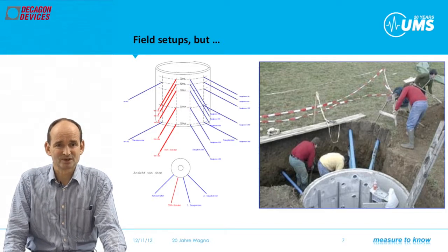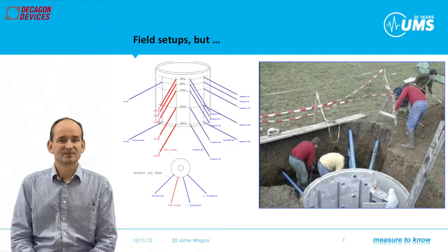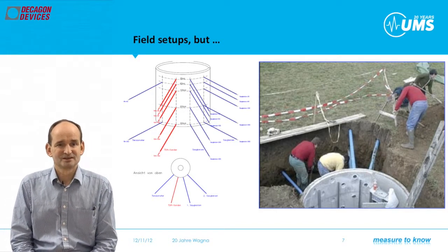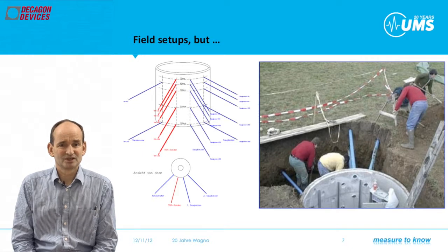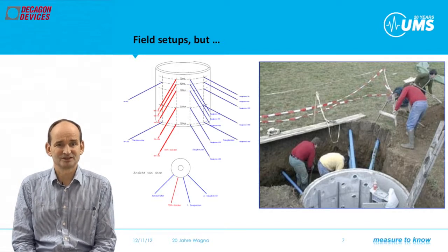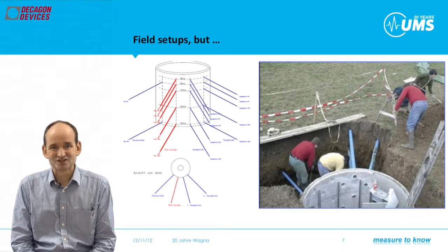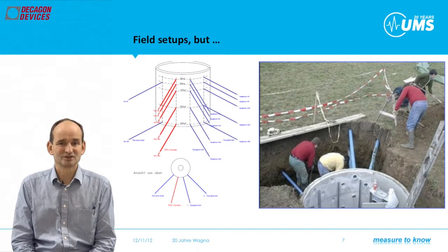Logger, battery and sampling bottles for soil water samples are mounted in the service well for long-term monitoring services. To calculate the groundwater recharge capability and the evaporation rates, the Hydrus 2D and other models are used. Therefore, we need the matrix potential differences, of course, in each layer and the according conductivities. The big advantage of this setup is not to influence the natural water fluxes.